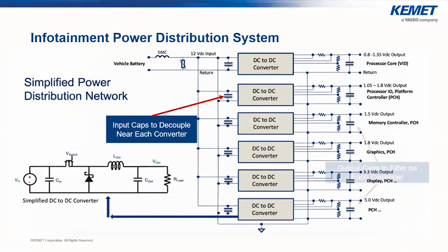Then you are going to go through the switcher. On the output of the switcher, you want to have a nice, clean, stable voltage, so that it is very friendly to the portion of the semiconductor that you are powering. To do that, you create a filtering network, and that is going to comprise two main components. That is going to be your inductor.